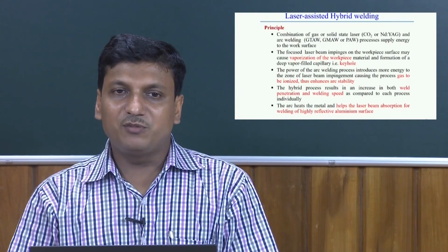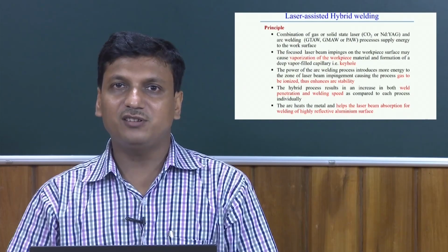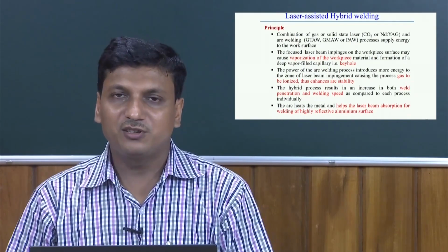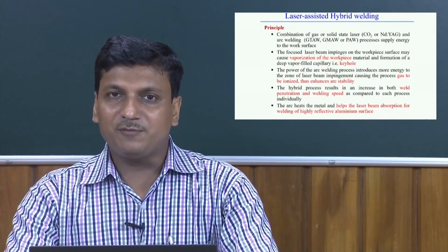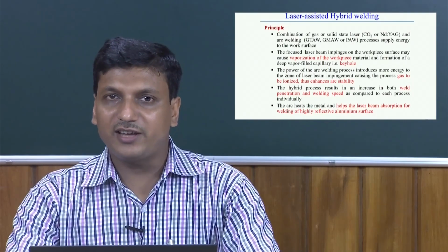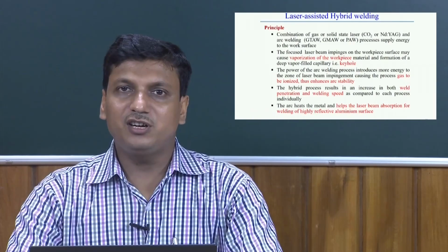Another specific principle it follows is that in the hybrid welding process there is an increment of the weld penetration. Basically, a high depth of penetration can be achieved using this hybrid welding process, and at the same time high welding speed can also be used as compared to the individual processes.